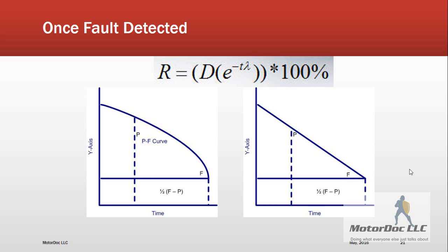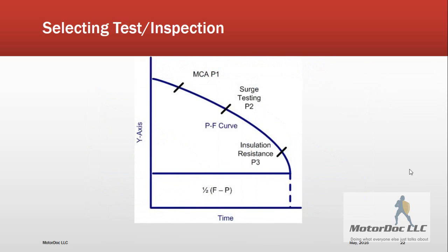There are two versions of the standard P/F curve. One is a logarithmic curve that relates to most random failure systems, and the second is a straight line that relates to most wear-out systems. The objective is to try to determine what the chance is along the P/F curve. As the one on the left is the most common, the formula that is simplest to use is the modified availability formula, as shown and discussed previously.